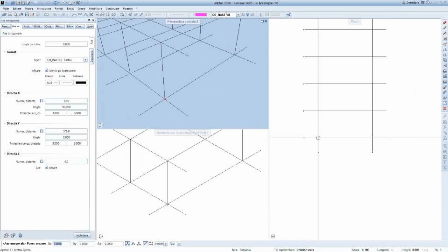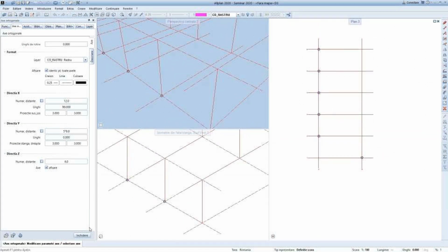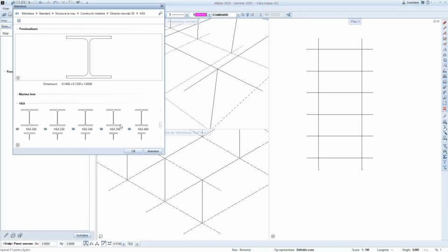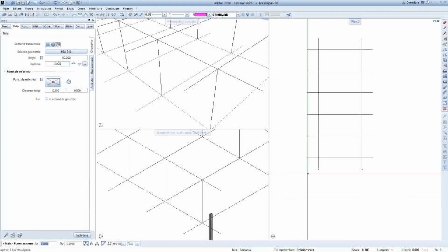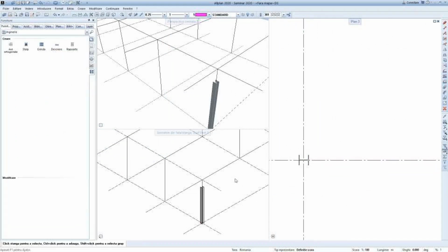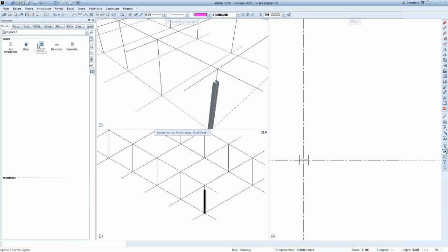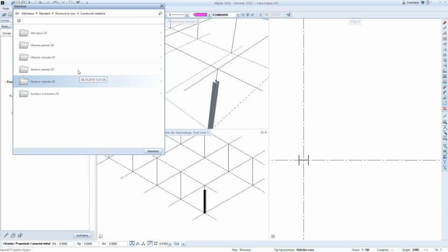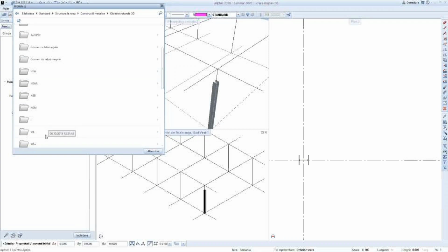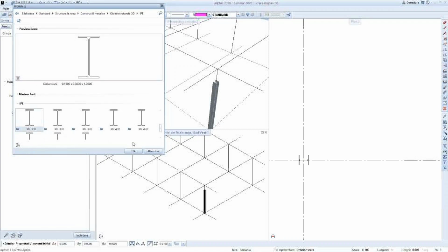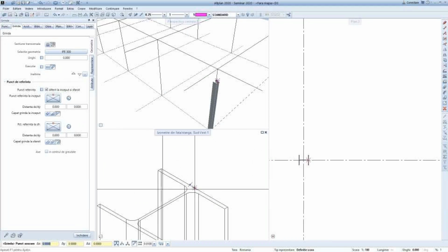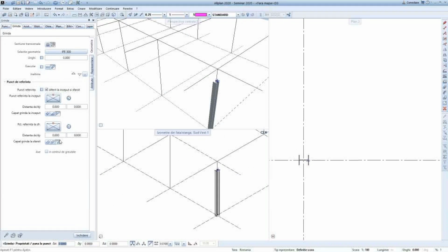And I'll just show you how easy we can make a steel hall now based on the new grid system. We go with columns from the database. You should choose the database of SIA, you impose those, but here I use the older database. You just start making a frame. We go now for a beam. I'll make half of it, and aside from the database that Allplan provides, you now have the possibility of making a sloped beam, a horizontal one, and to control the cutting of the item.